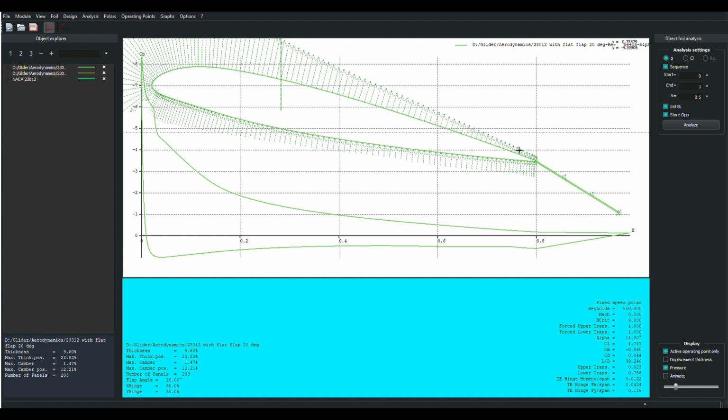Here we are, we look at the hinge point of that flap at the trailing edge, and we notice we don't have that wall of adverse pressure gradient here getting in the way. We don't have a big spike in the pressures back here. We don't have a big drop in pressure at the leading edge of the flap, which caused the wall to form and make it hard for the flow to go forward here. And